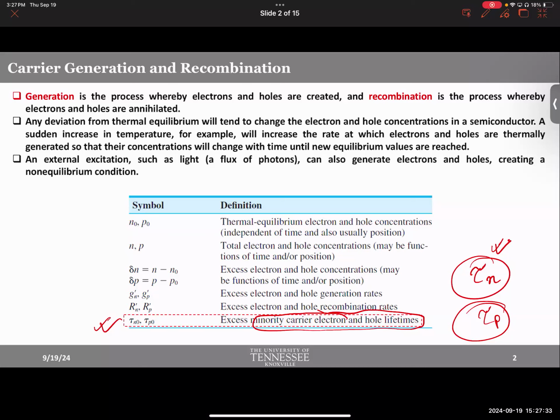So if you have a material in a solar cell that has a longer lifetime for carriers, meaning what is lifetime? Time difference between generation and recombination. How long it takes to get recombined and go out of picture, right? A nanosecond, 10 nanosecond, 20 nanosecond. If you have a material that has a longer time frame, that gives you more time to separate out or filter out the electrons and holes.